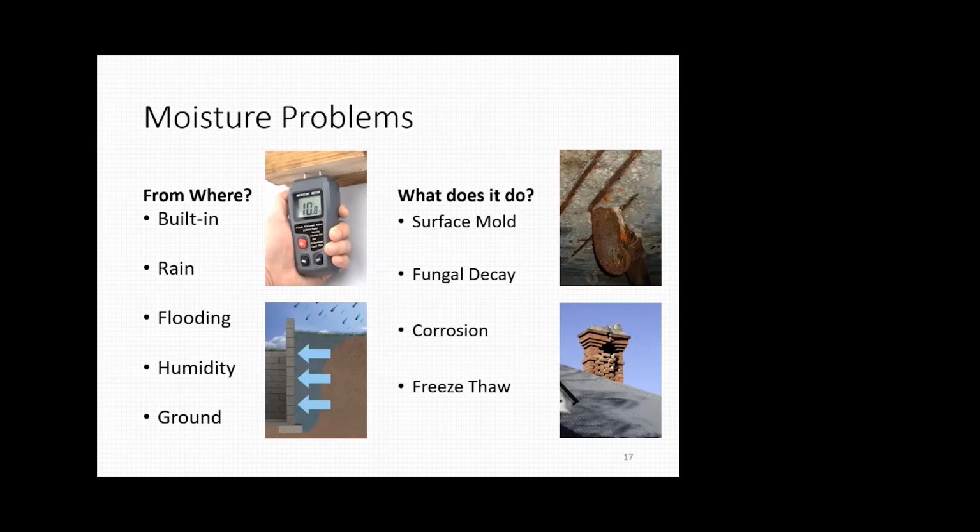When you design a wall and don't take into consideration the hydrostatic pressure it will experience in heavy rains, it could cause failure in this wall. It could collapse, or it's definitely going to crack and start leaking into the basement at some point. This is all stuff that causes issues with structural durability.